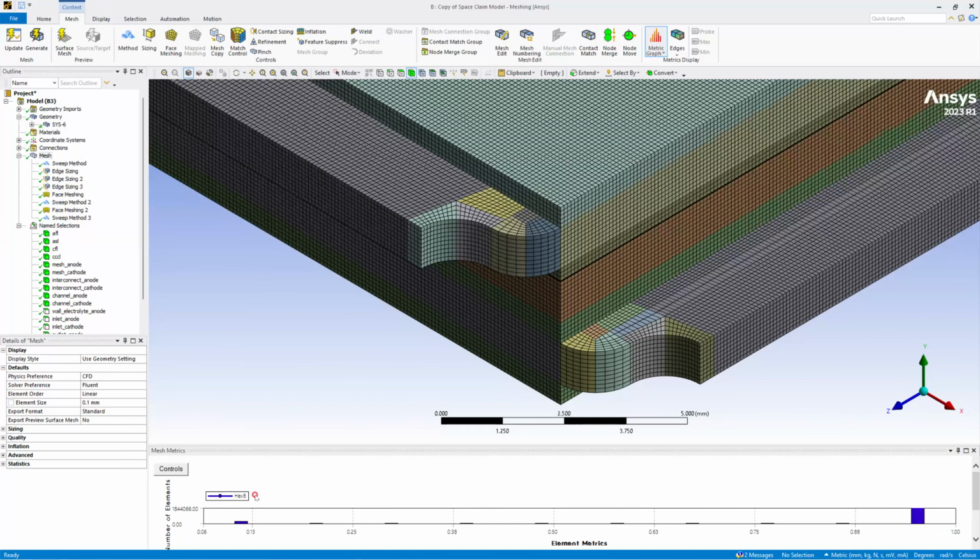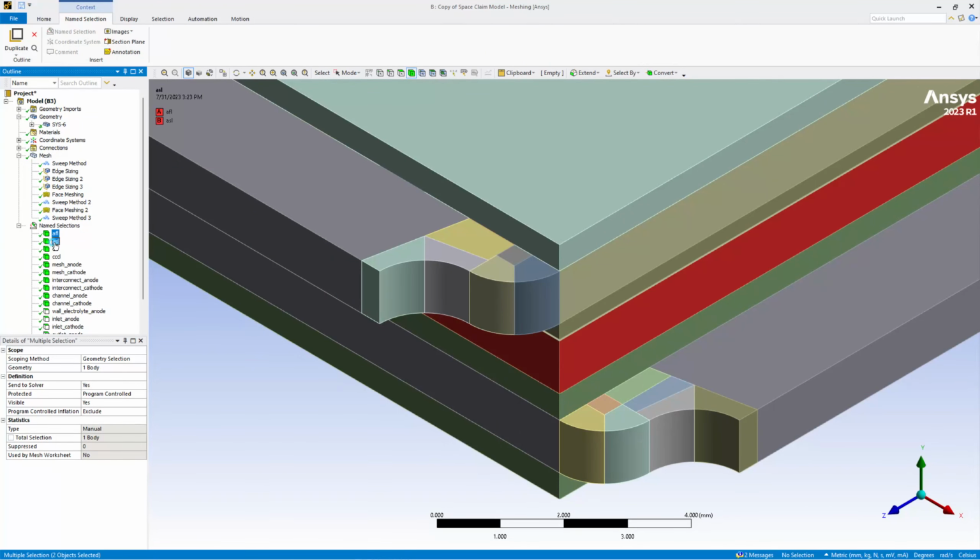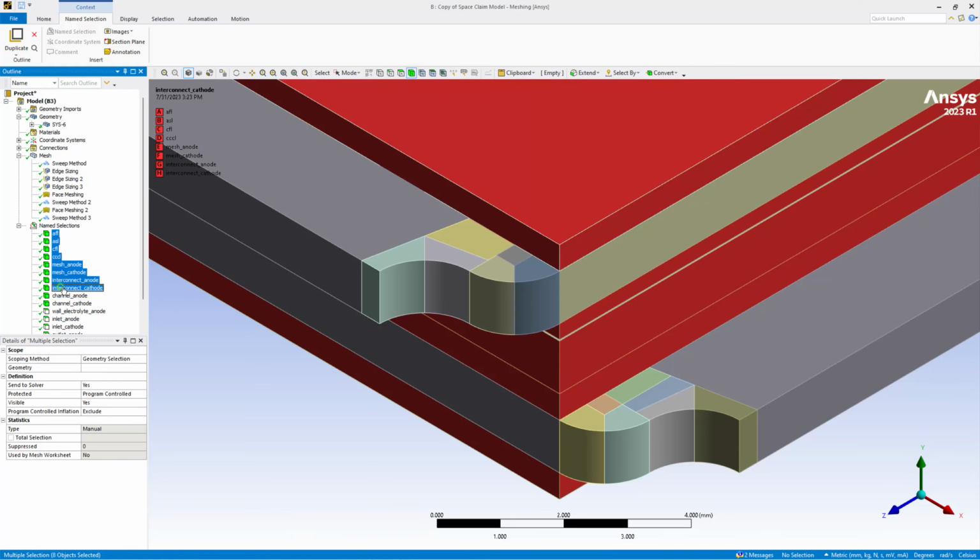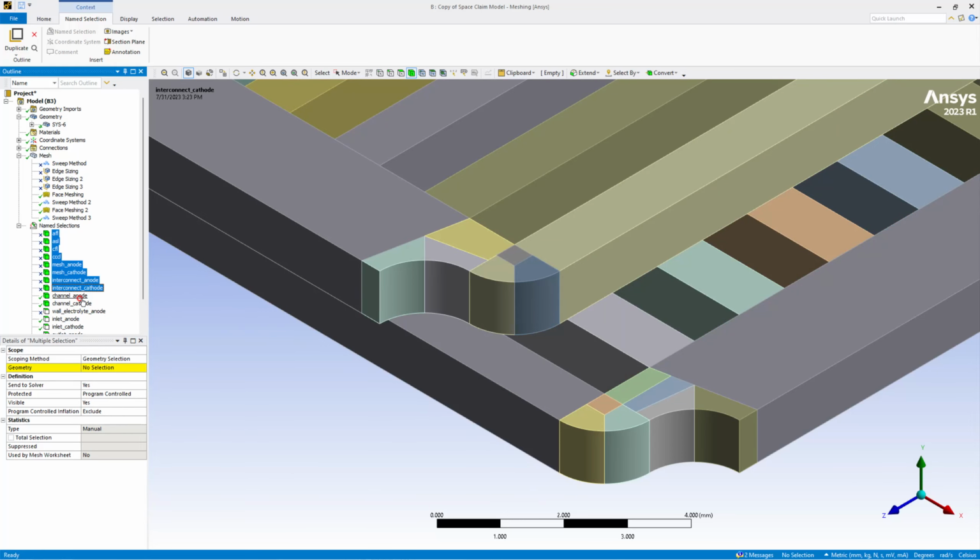As you can see, there's no other mesh labels that were present previously. And to check the mesh quality for the gas channels, we should suppress all the other components. So we'll suppress them temporarily, suppress bodies and group, and check for the mesh quality now.